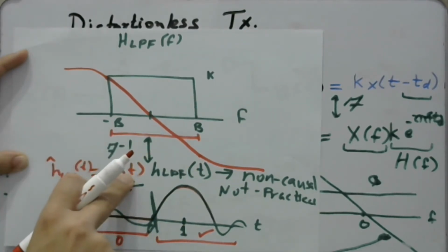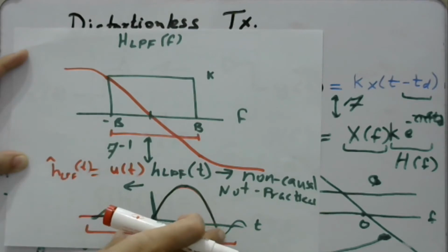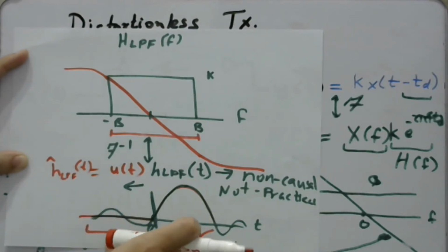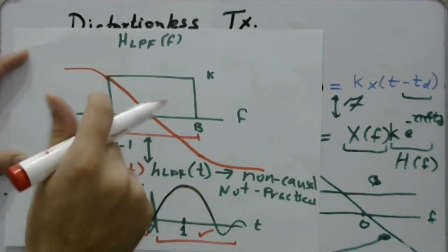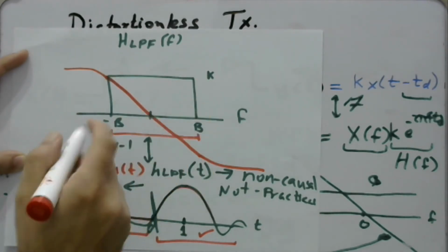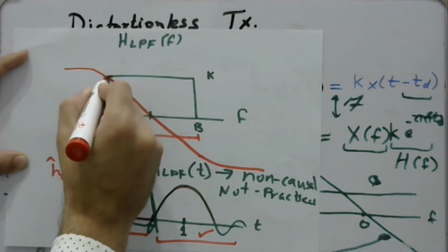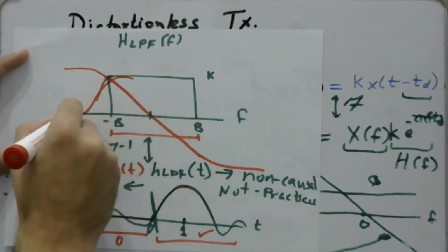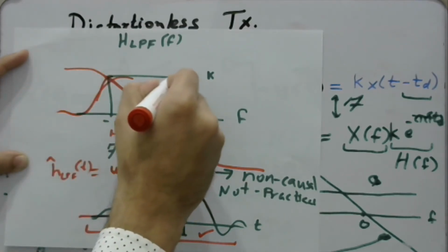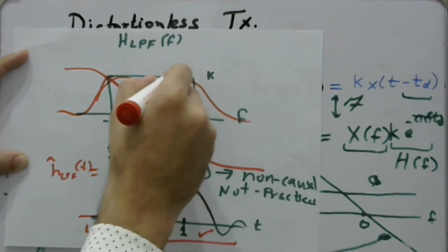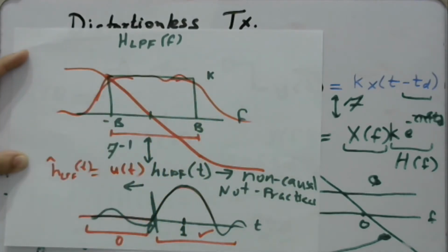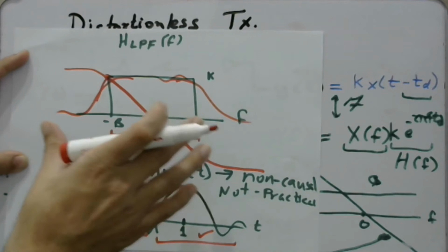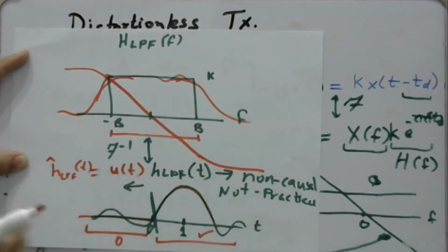Multiplication by the unit step function has changed the behavior of the system in the time domain. So the frequency spectrum or the frequency plot would also change, and we would lose this sharp cutoff and have something like this at the edges, with some transitions over here. In this way the filter or the system is becoming more and more practical.